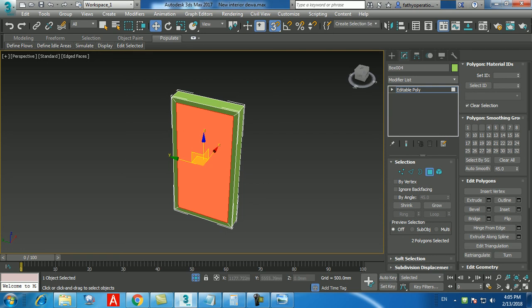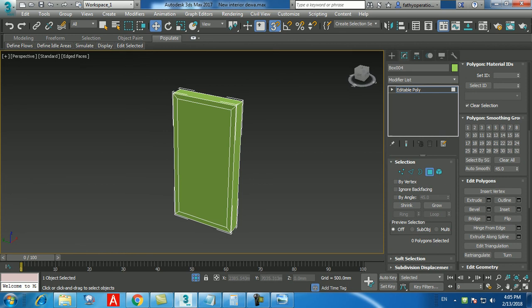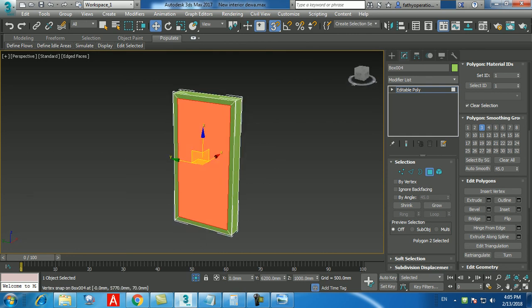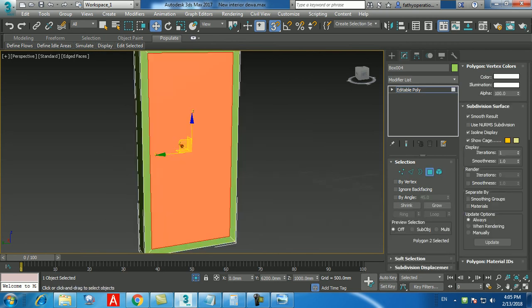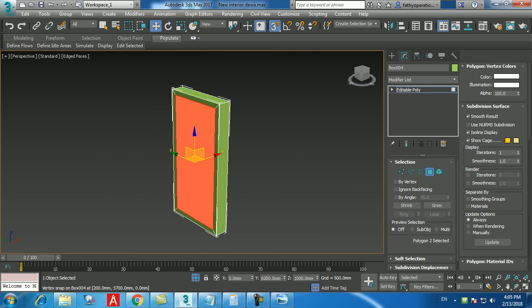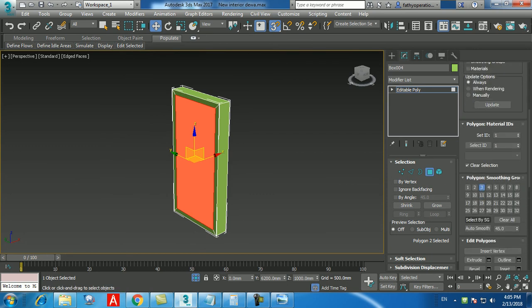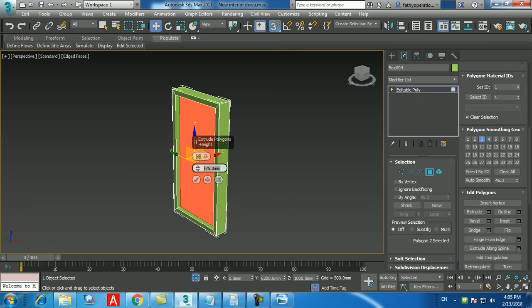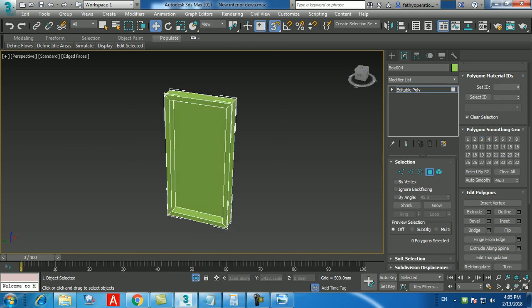Okay. Once you finish inset, select only the outside face. This is outside. This is outside. This is back. Because many times it is rotated. Okay. If you want, you can unisolate to check it quickly. So you can quickly know where you are exactly. Extrude minus 150. Only the outer layer you should extrude. Yep. Or multi. Or box also. Minus 150.